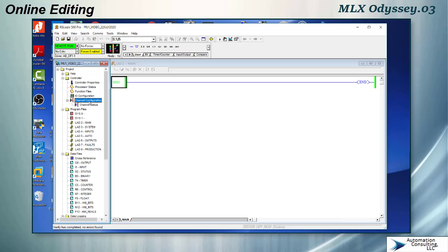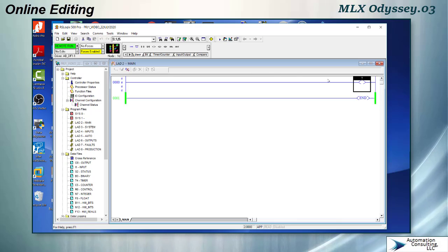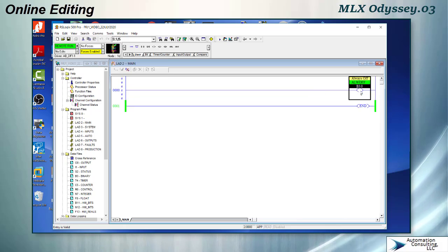I'm going to add a couple of quick contacts here. We'll do some subroutine calls and things also. So remember, in the previous video, we put an always on and always off bit, B3/0. And notice that was the always off that we created in the previous video. I'm going to change this to a 1 because we want it to be always on. And then I'm going to use a different method to create my always off.